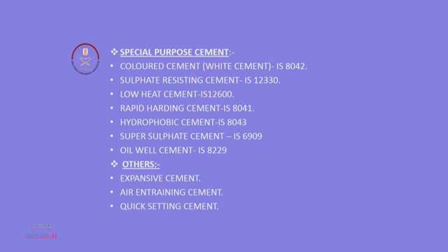Like the name shows, expansive cement, due to its virtue, performs better whenever grouting of bolts and that type of use is required; there, expansive cement is utilized. In air entraining cement, when it is utilized in concrete, automatically by virtue of the cement, some air pockets are created.